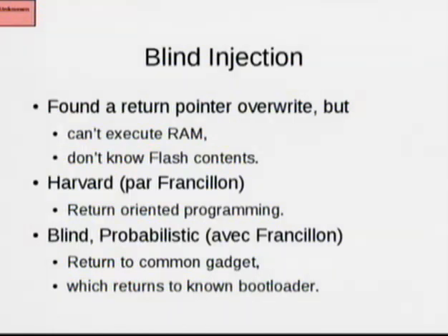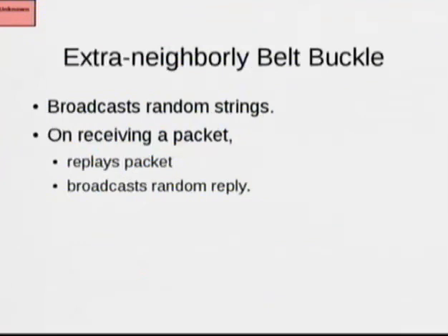In the case of Harvard chips, Aurélien wrote a neat little paper on using return-oriented programming for microcontrollers, in which he was actually able to use enough of the existing code in a wireless sensor to move an exploit from RAM into flash memory so that it could be executed. And he did all of this movement without being able to run any of his attack code. It was at CCS in 2008. It's well worth looking up.